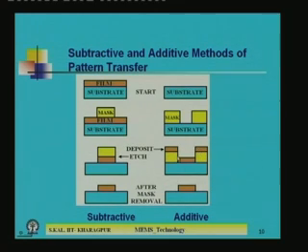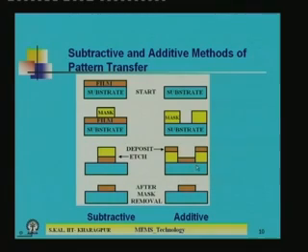So, if you can get a thicker photoresist film, for that you have to use a special kind of positive photoresist, whose viscosity is more, and by which you can pattern larger thickness resist. Okay. So, this is one condition. If you satisfy it, then easily you can pattern without knowing the etching solution of that particular film. So, this is very much used in many cases of pattern transfer.